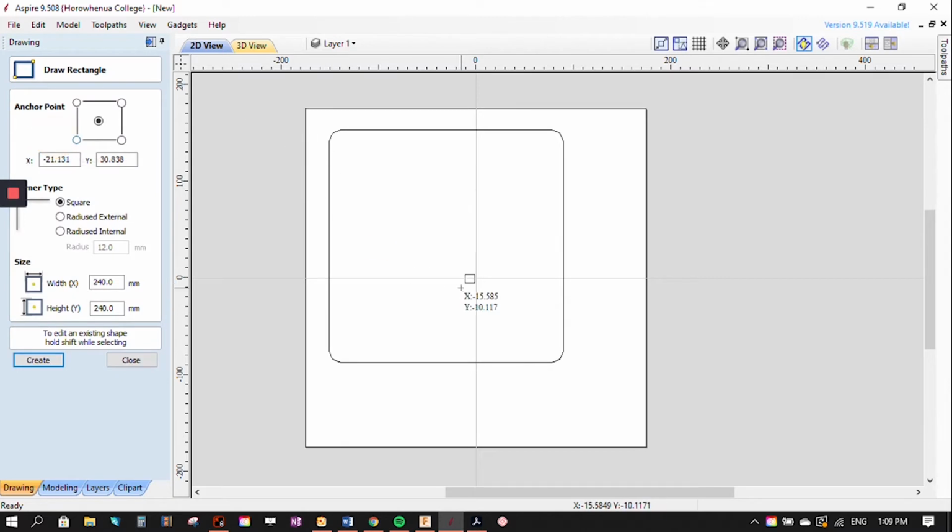Right, so we do another drawing here. Now we want this particular section to be, as it said, 18.5 millimeters high. Oh, sorry, that's the bottom one, 0.5 millimeters high down there. And the top, it says 90, but we're actually going to make it 120, and I'll show you why in a moment.